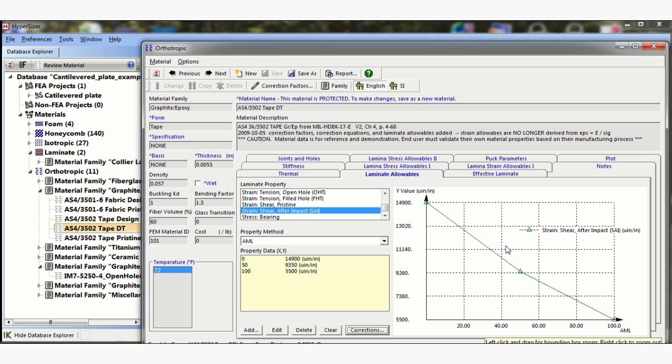What has to be traded off is the cost of the test plan for laminate analysis versus laminate, and much depends how you go about it. But from a stress engineer perspective, if I just ignore how much the test costs, I would much prefer to use a laminate analysis methodology for my modeling loads and for my stress analysis.